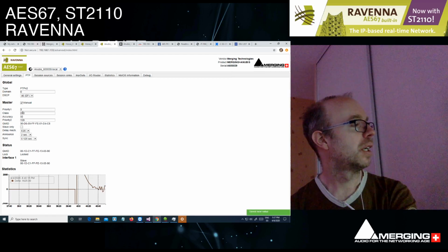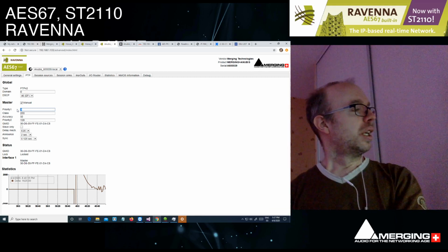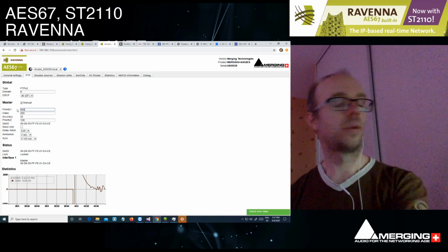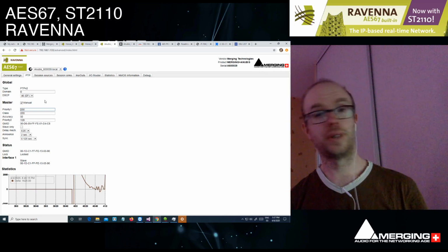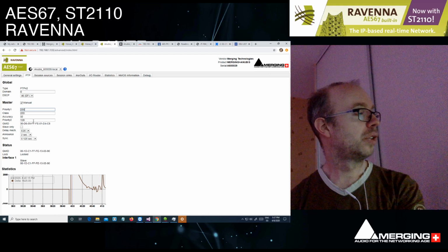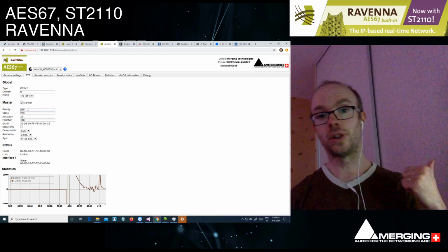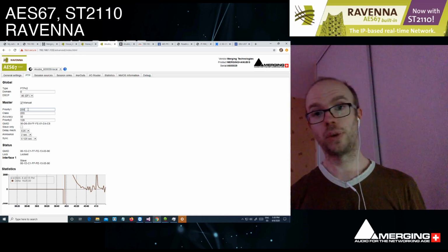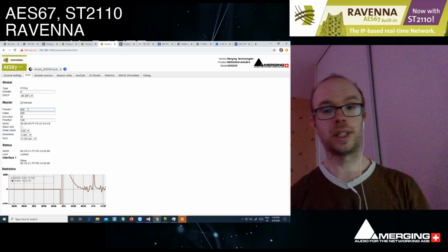I can always also do that. So mainly the thing that you have to care about is the value of priority 1, and set it. The lower the value of priority 1 is, the higher the chance of it being master will be. So if I set it to 250, for instance, the device will not be master, even though slave only is not checked. The actual Dante devices on the network have a PTP setting of priority 1 that is lower than 250, and so this device is not taking the role of master.